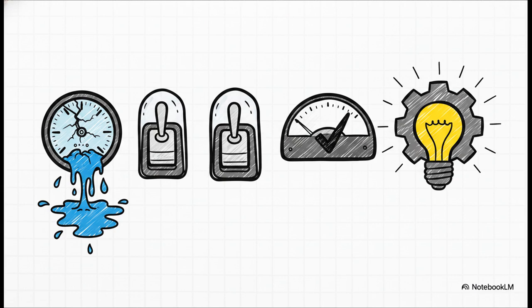The program controller also maintains the critical status flags. Think of these as the control panel warning lights for our factory. You've got the overflow flag for when the math gets a little too big for the ALU. The interrupt mode bit, which globally enables or masks those interruptions we just talked about. The test/control bit to store logic results for branching. And finally, a very special one called the CNF bit, which actually configures our on-chip RAM.